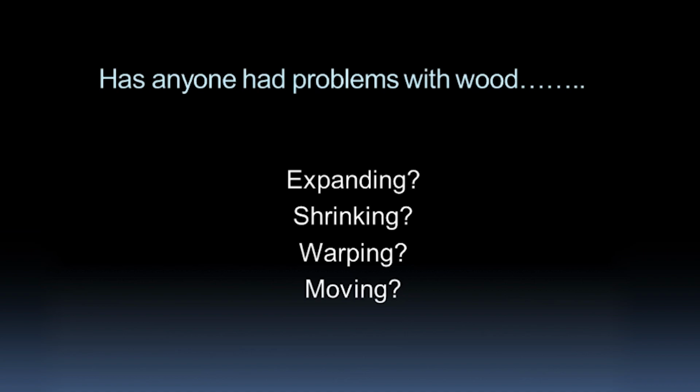How many people that are doing commercial work, I guess primarily, and maybe even residential work, put humidity readers, data loggers on site to track the level of relative humidity on the installation sites that they are either installing on or preparing to install on? Very, very important.